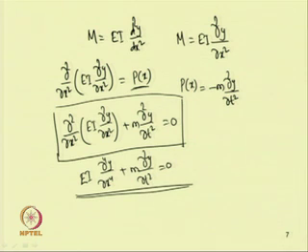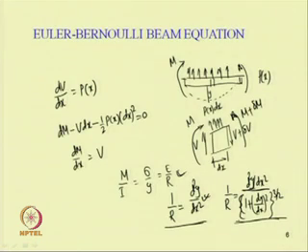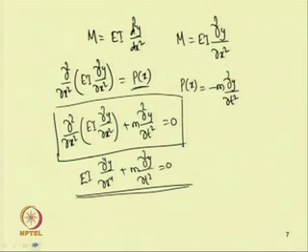So, if one takes large deflection, in that case this 1/r will be replaced by ∂²y/∂x² divided by (1 plus (∂y/∂x)²) to the power 3/2, and one can expand this term by taking this to the numerator and have a nonlinear equation. So, let us first solve this linear equation, or let us see what is the importance of this equation or how it can be solved.